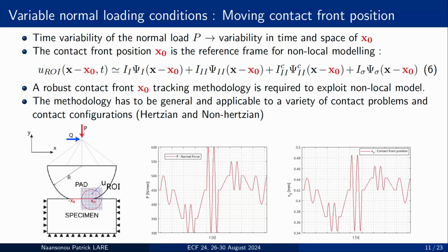But to use the non-local approach in equation 6, I need to know the contact front position to extract the intensity factors that I need. So for that, we developed a robust contact front detection methodology to track the contact front position. The methodology that we developed is general and applicable to a variety of contact problems, and is able to work if the contact configuration is Hertzian or non-Hertzian.